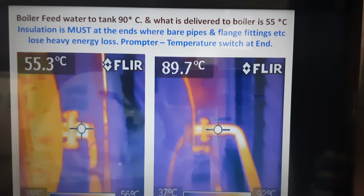Coming to the thermal imager, every thermal imager we are using in the industry is dedicated only to the powerhouse or limited to electrical applications. But a thermal imager has excellent scope in seeing the temperature gradient throughout the process, in any main or branch header or any equipment where the temperature is above ambient. You can definitely assess the temperature gradient, what is optimal, what is normal, what is abnormal, what the deviations are, and how they can be addressed.